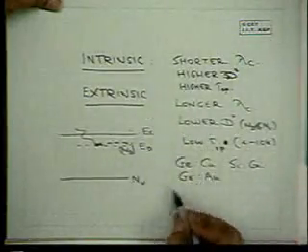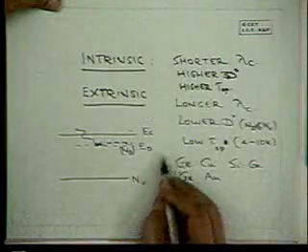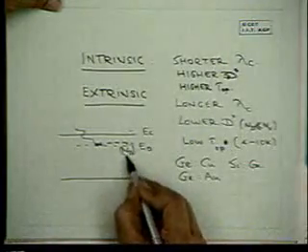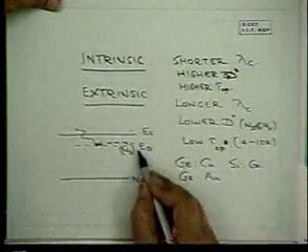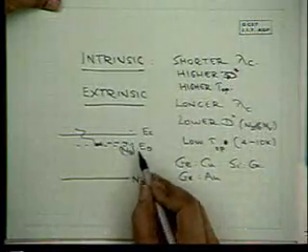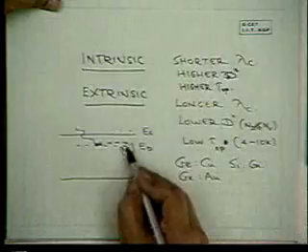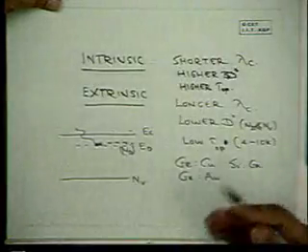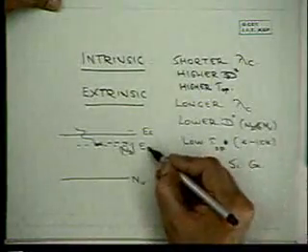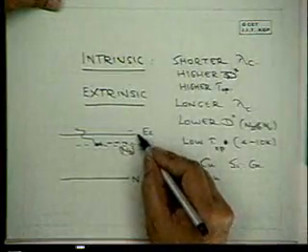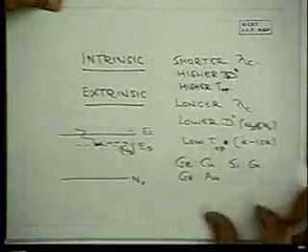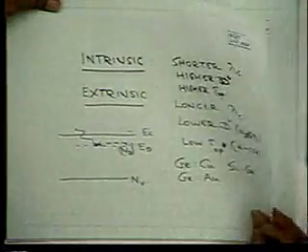Obviously, in this case, a crucial consideration is what is Nd? What is the heaviest doping that you can do with copper in germanium or gold in germanium? Okay, so the heavier doping that you can make, then obviously the sensitivity will increase. But on the other hand, there are other effects, like if you do very heavy doping, then these levels may merge with the conduction band. Okay, then there will be a continuum. So then there will be problems there.